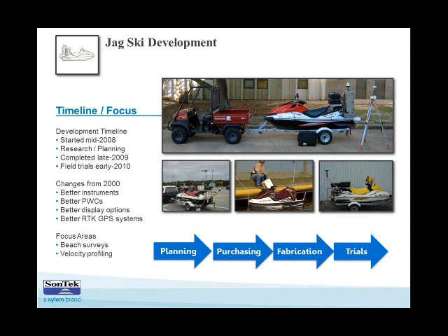The CTD integration is also very good, as it is and has been in River Surveyor Live. So we use our CastAway CTD and then bring those data in after the fact when the survey is done to correct everything. There's very little extra work that you would really need to do to develop your bathymetric survey using HydroSurveyor. Your elevations now are absolute. If you're working with your RTK system, they're also very accurate.